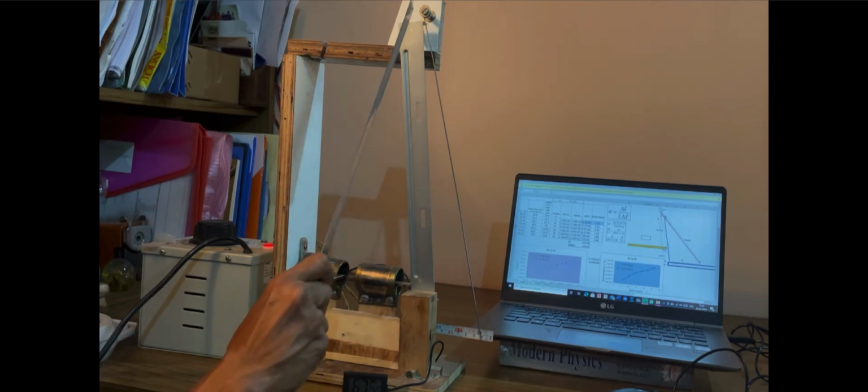There is a second lever which is pivoted at this point, and it is again resting at the free end of lever 1. This distance is 1 centimeter, while the overall length of the second lever is 40 centimeters. So when this shifts through 15x, this point shifts through 40 times 15x, which is 600x. And therefore, if the small expansion x is not noticeable, 600 times x will be noticeable on the scale that has been placed just behind this.